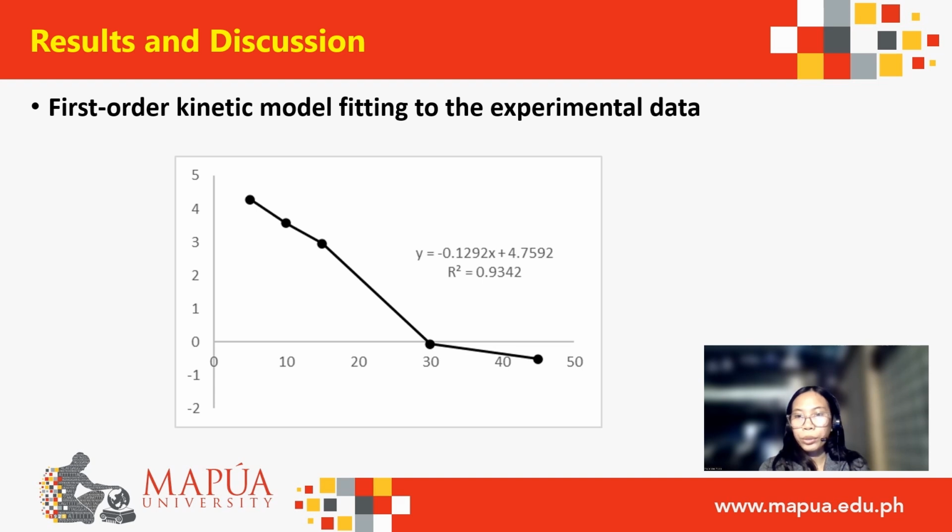So after we have observed the optimum conditions for the parameters, which are the FeAl electrodes, 0.3 amperes, and potassium persulfate, we did a kinetic study regarding this in order for us to determine the amount of OTC removed during different durations of the EC process.